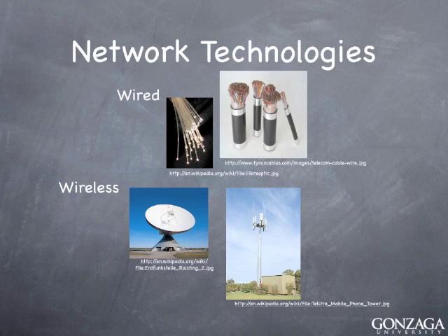Depending on the size of your service territory, though, you may find that it's just not cost effective to be able to lay wired communication transport everywhere that you need to connect to endpoints. In which case, then you're going to go into wireless. Wireless is going to be driven by what your access to basically line of sight locations would be.